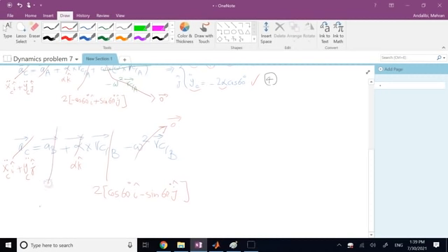And finally, A of B, what is that? I don't know. It has a magnitude that I don't know, but it is definitely positive j or negative j. Now I know it's negative j. It's coming down from 0 speed, so you need a negative velocity. And negative velocity comes from a negative acceleration if your initial velocity is 0. So I know it is negative j, and I can assume it's negative j, but it's okay. I can just use the direction, use the line of action. Again, this gives you 2 equations, one for i, one for j.